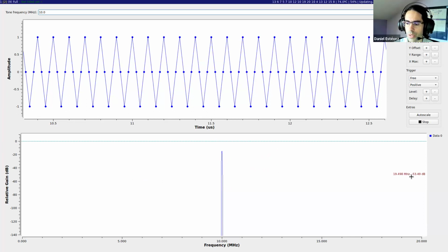megahertz. So let's think that we have this signal at 10 megahertz, and we want to receive it with the RTL SDR. But we saw in GQRX and also in GNU Radio that the RTL SDR doesn't support 20 mega samples per second. The maximum sample rate it supports is 3.2 mega samples per second. So how can we proceed now?